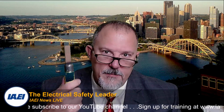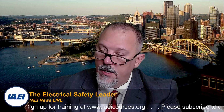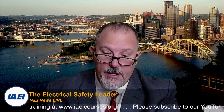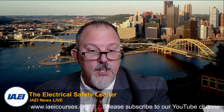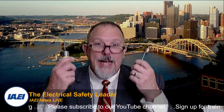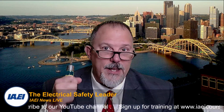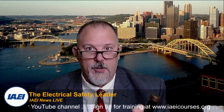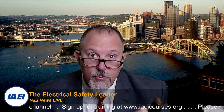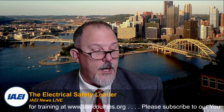One of the nice things about this fuse, and I'll give you an example. I've got two fuses here. This is 600 volts AC, 300,000 amps interrupting rating. This is 600 volts AC, 200,000 amps interrupting rating. Do I have to worry about exceeding the interrupting rating when I've got a 300,000 amp or a 200,000 amp interrupting rating fuse? I don't think so. I've got 600 volts.